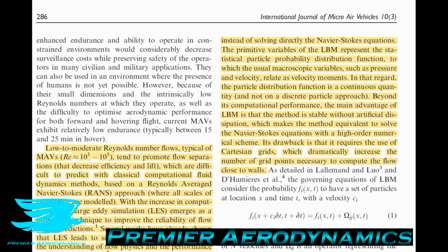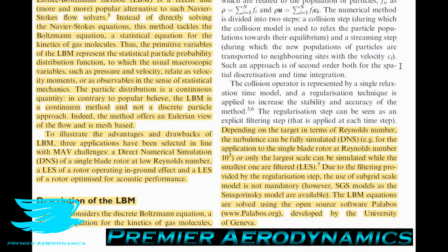So when they're saying that this is one of the drawbacks, I believe that this is a drawback that will be solved quite quickly, at least not in the distant future, in the near future. There are other drawbacks for the LBM method, for the LBM approach. And there are some arguments that can be made that it's been oversold in some senses, but even though it has been oversold in some cases, for example, one major drawback of the LBM approach is that the time step that you specify is usually implicitly specified. So you can't really specify it explicitly. At least that's one of the problems at the moment. But I think that will be solved as well. So that's why the LBM approach has such huge potential.